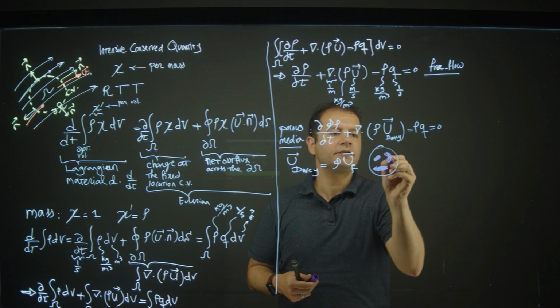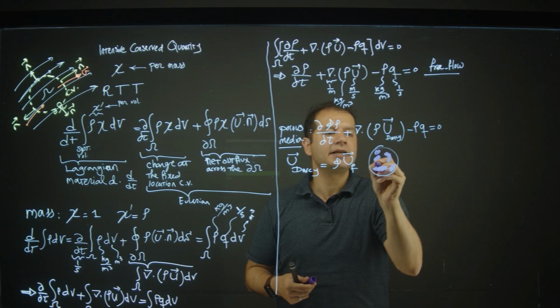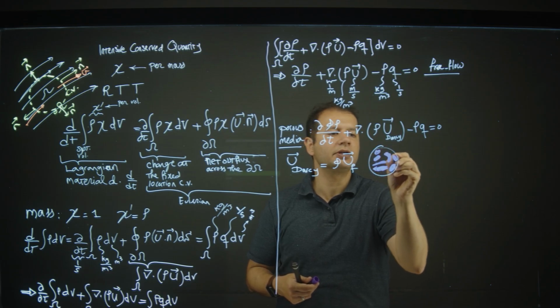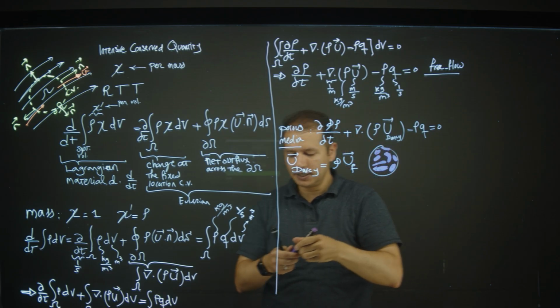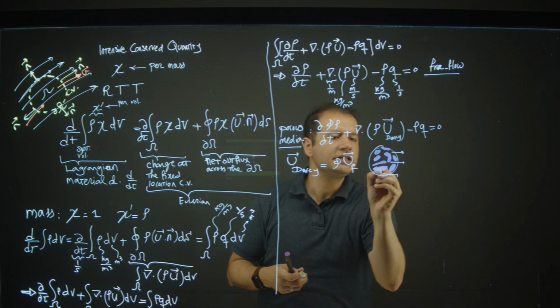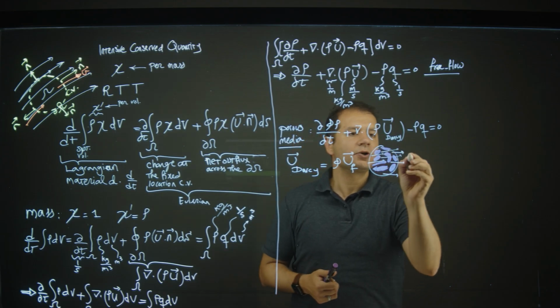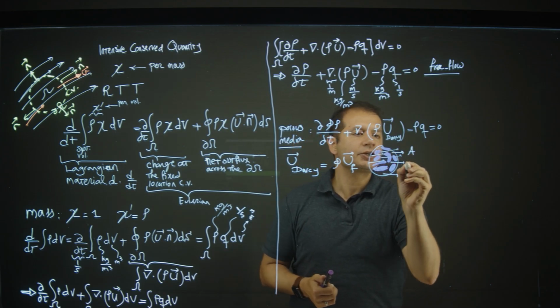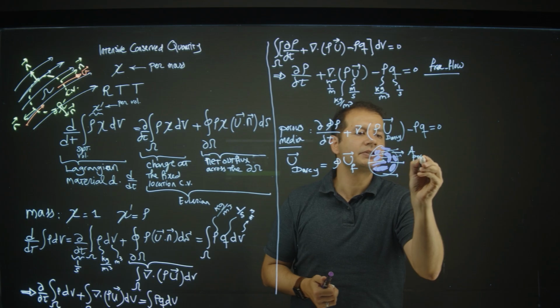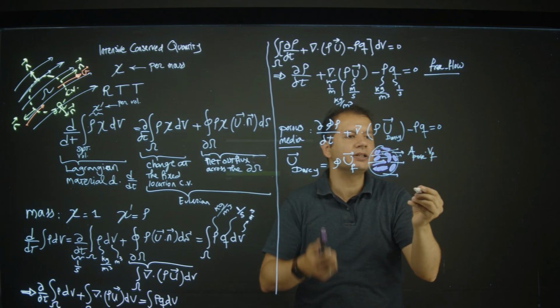The flow is only inside the porous space and not through the grains naturally, because this is the solid part. Then I know that fluid is only flowing through this kind of void space. So the cross-section area of the porous space times the velocity of the fluid, or U of the fluid, doesn't matter.